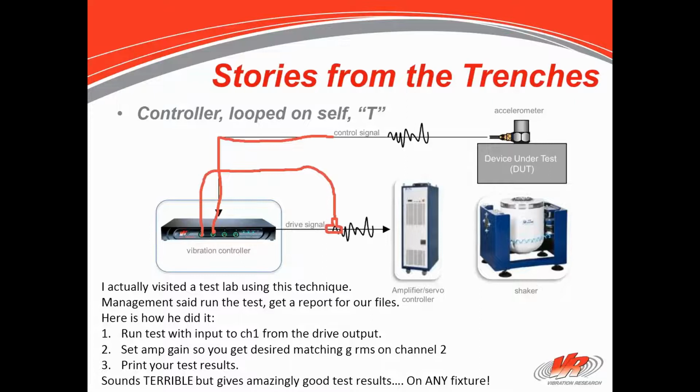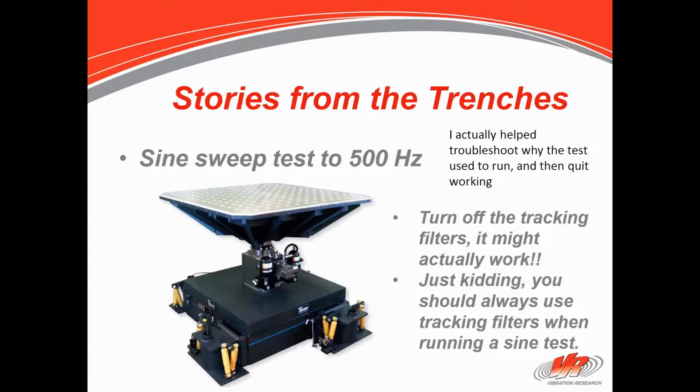My next challenge question was, well, you're running a 15-minute test on this product. You actually only had the amplifier running for probably 12 of those 15 minutes. And the answer for that was, well, I really run the test for about 20 minutes just to make sure I had an acceptable amount of vibration time on the product. So that will give you the print that you want, put it in the file, but it's the wrong way to do it. And you can rest assured that solution number 2, verifying the strength of your product, was not accomplished. Don't do it.